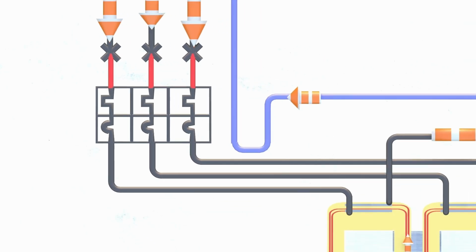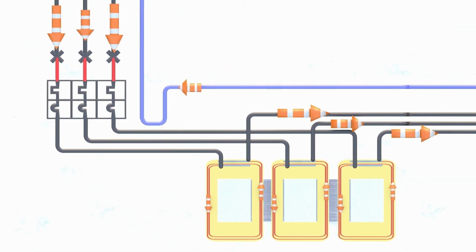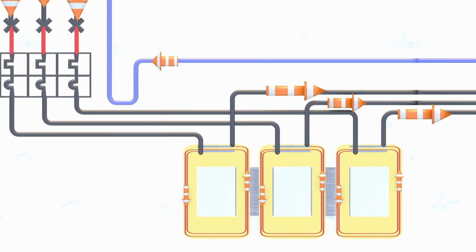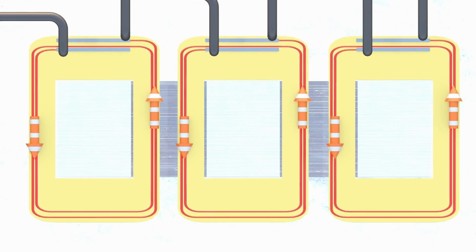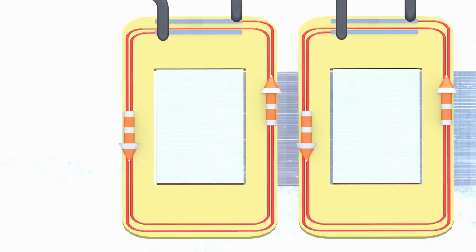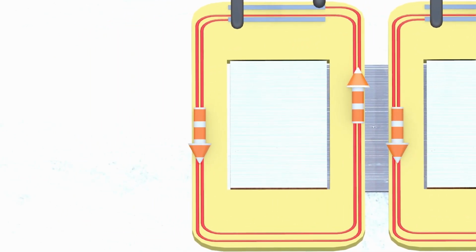The phase currents are now flowing through the main winding. Already now, the main windings feel like a drag. We limit the inrush currents and dampen the harmonics, according to the function of a choke coil. But this well-known technique doesn't seem to work against asymmetric loads on the power grid. There is still a current flow on the neutral conductor, going back into the medium voltage transformer.